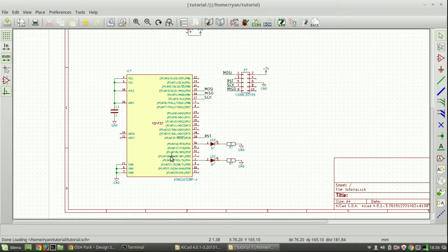To figure out what footprint you need, you'll need to find the part that you want on DigiKey or Mouser. This is going to be a real thing that you want to buy. It will define all of the sizing and footprints that you need for the PCB. Typically, look online for these parts.